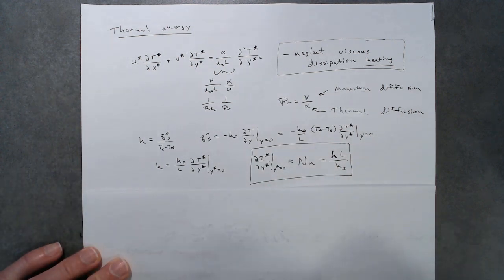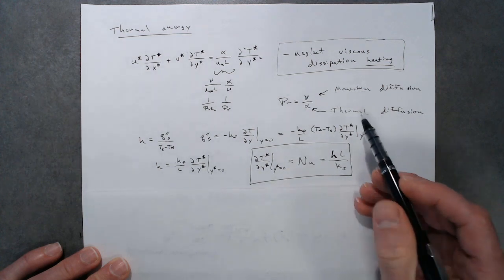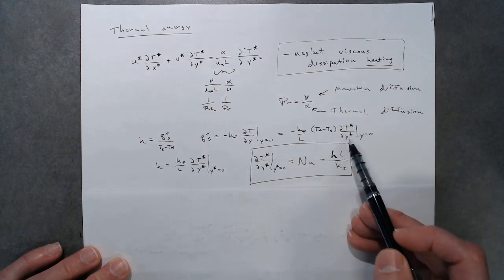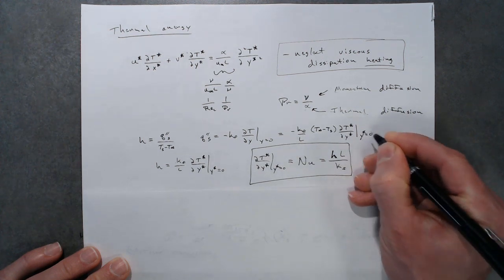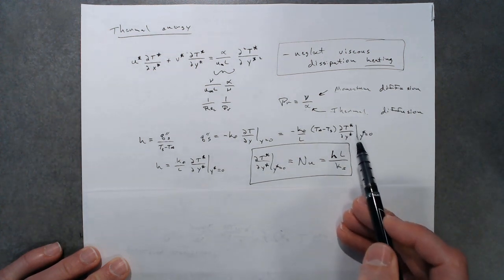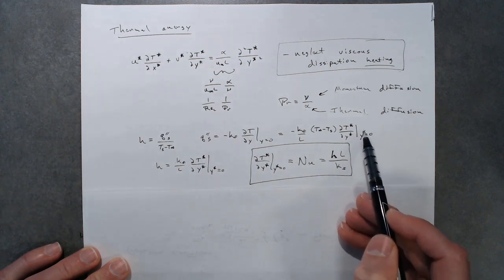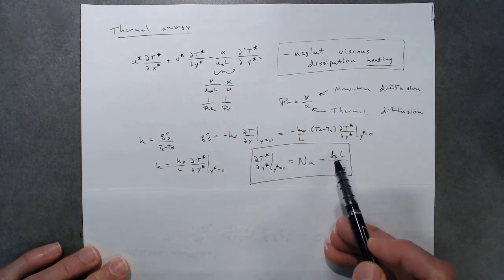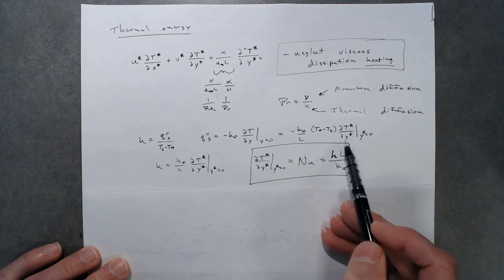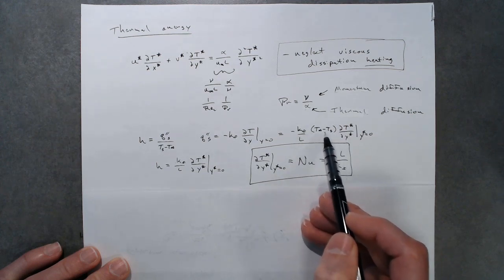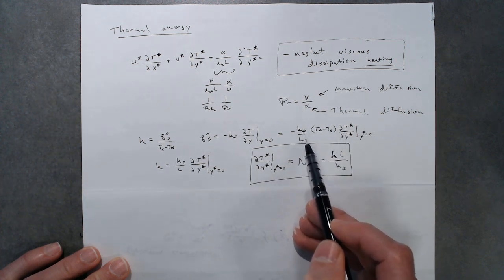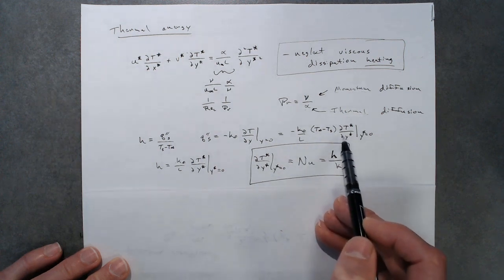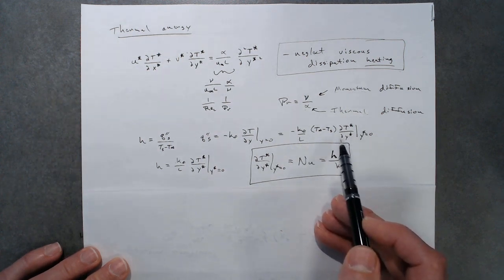And if we consider our non-dimensional definition of temperature and position y, then our gradient in temperature at the surface, y star equals 0, is equal to the non-dimensional gradient times T infinity minus Ts. Again, that's just from our definition of T star, times k_f over L. Again, the L comes from our definition of y star.